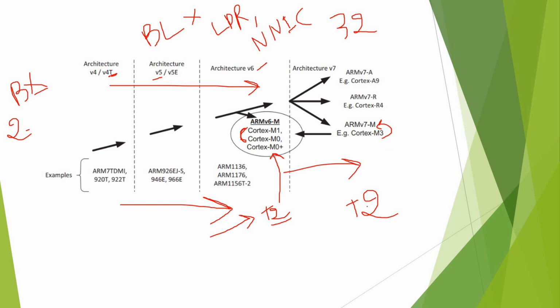Back to the Cortex-M3. Besides the support by default for T2 or Thumb-2, there have been extensions to some other blocks that were introduced on ARMv6M, like the NVIC. So now we have support of up to 240 interrupt lines. The MPU is present as well, and it can cover up to 8 regions. The hardware-based context switching of interrupt enter and exit is also still there and fully managed by hardware. And there are many other features that we are going to explore within the next lectures and slides.